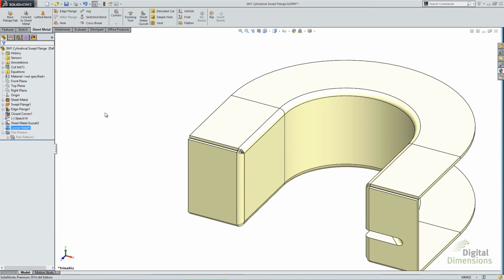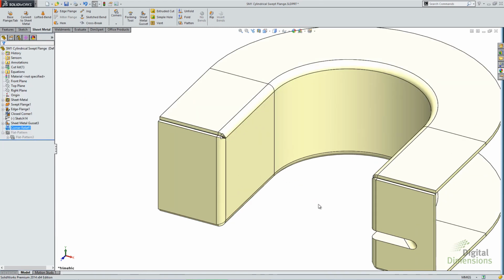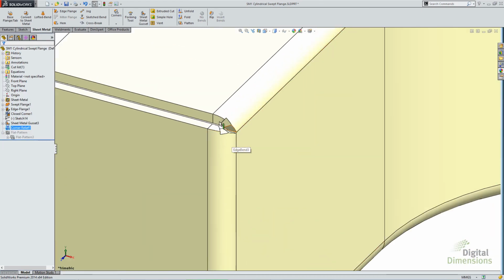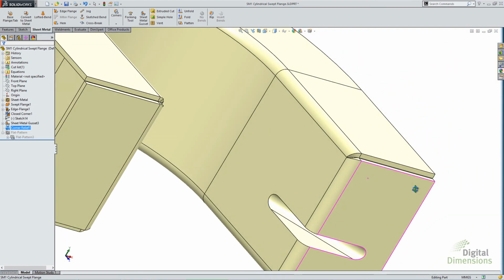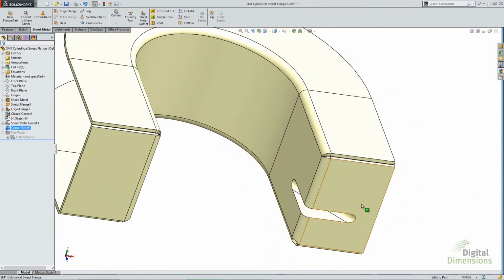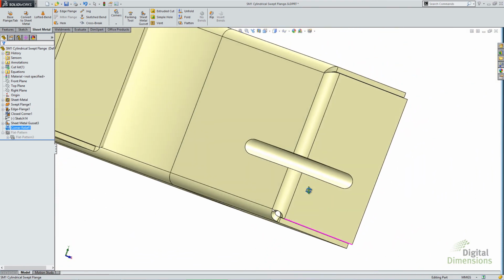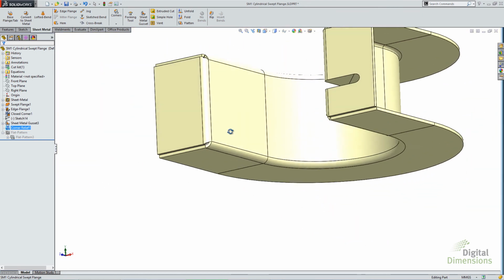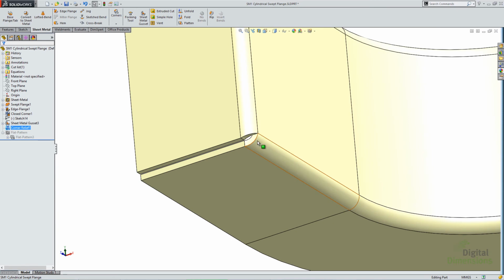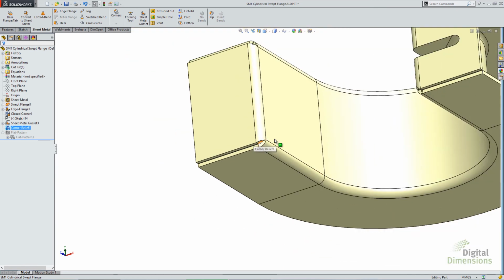Let's go ahead and click OK, and then zoom in here on some of these different corners. So there's my rectangular relief. I'm actually seeing this relief now in the folded state. There's my constant width and my obround or circular, and then I believe, actually, that's constant width. I believe the other one was a tear.